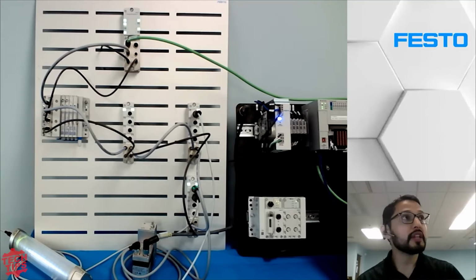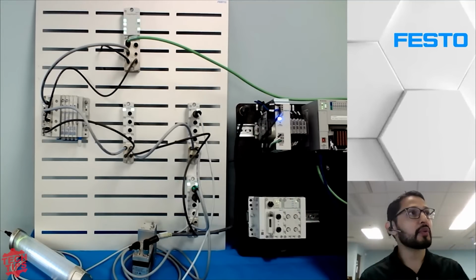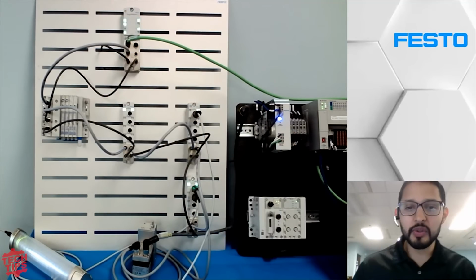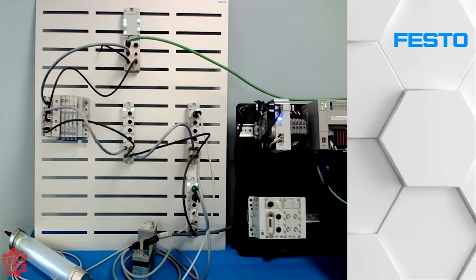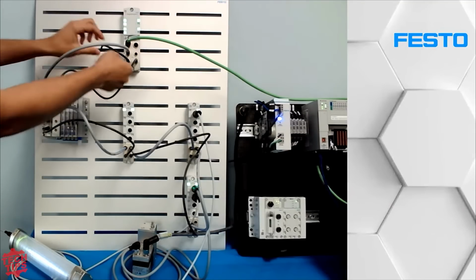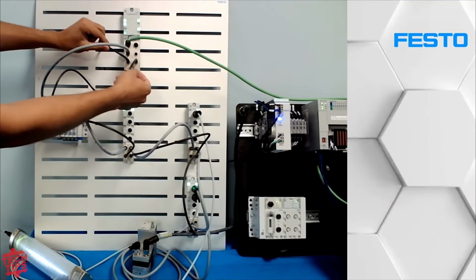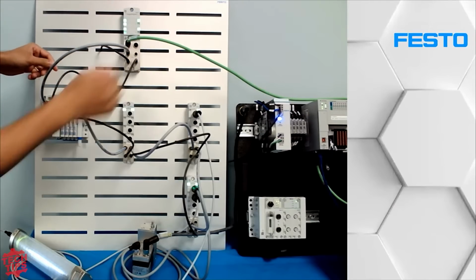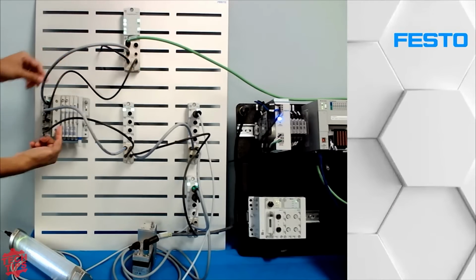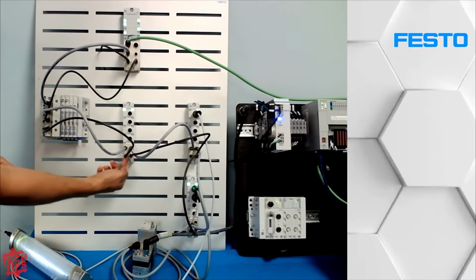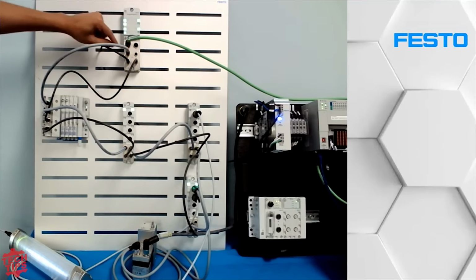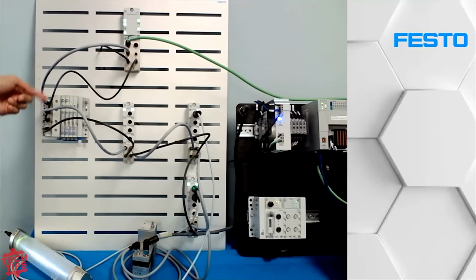This is how you set this up. You basically connect all of the modules. So I have the main module, and actually let me step over here so I can show you. What I did here is I started with this main module and put power to it. So this is going to my power supply. And then from here, as we mentioned, I do a daisy chain connection to all of my different modules. So I go in here, come out, go in the valve manifold, come out, go to the next one, go out, and so on. Same thing happens with the communication with the AP bus. So I go out, come in, go out, come in, and so on.